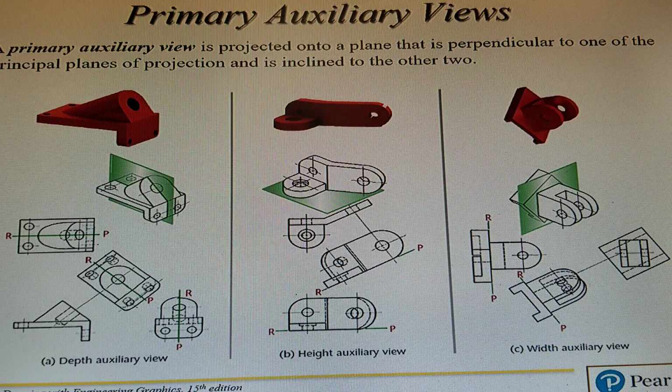So you have a front view there and a right side view, and you're going to project. You're trying to get that base, the piece on the left, as true size and shape, because in the front view, that circular pattern or that arc and that circle is true size and shape. But on the left, the way that thing is turned, you have to draw that auxiliary view from the side view to get the true size and shape of that base. Okay.